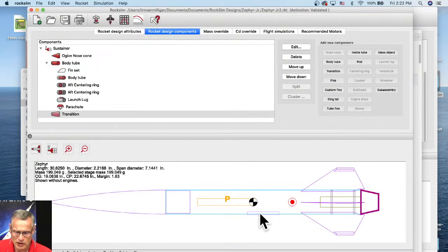So that's okay. So that should answer that question. So you can, Carlos, you can do it both ways. Both ways that you said will work. There's advantages and disadvantages. The advantage of doing the last way of changing the material is that you get a more accurate prediction of the center of gravity location. The disadvantage is it takes more time to set it up. But once it's set up, then it's fine.